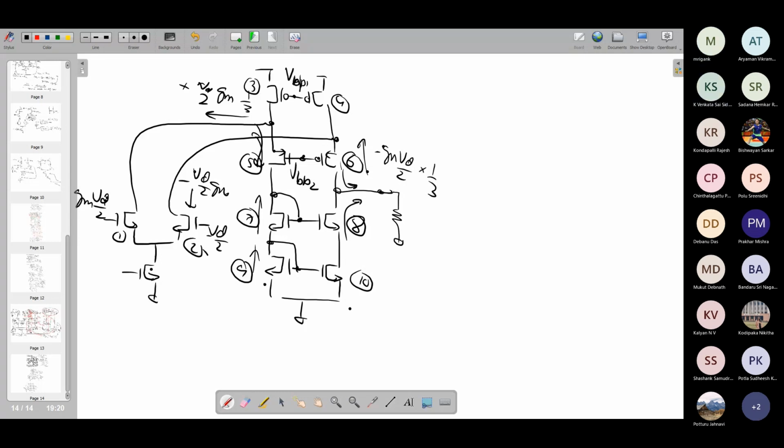Yes, sir. And now, generating these voltages, again, we can make use of a similar strategy, because we know the W by L of M4 and the current. So ultimately for M4, we are going to take a current source because we need a certain bias current IB. So you have some IREF, and from that IREF, you are biasing M3, M4 to get an appropriate current at this point. So the VB, the gate voltage of M3, M4, is simply coming from a current mirror in this particular scenario.